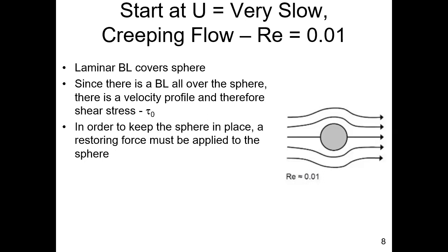If the sphere was sitting here and the flow was moving by it, it would push that sphere in the direction of the flow. So we would need some type of restoring force to hold that sphere in place against the forces of the fluid. What are those forces? It's the shear stress all over the area, integrated over that area.